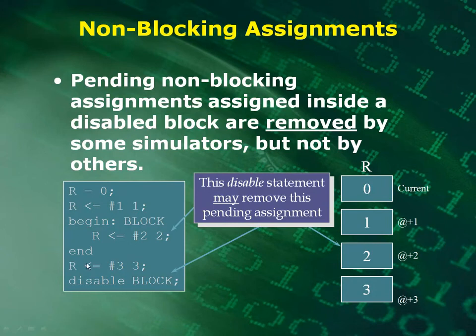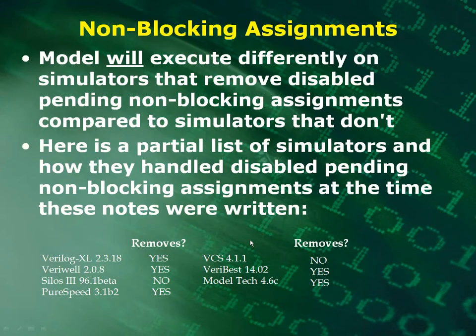Now remember these are non-blocking, so there's no time, we're still in the current time step, and then all of a sudden we said disable block. Well, some simulators may remove this pending assignment from this block, which was r equal 2, and some may not. So this is something you have to be aware of.